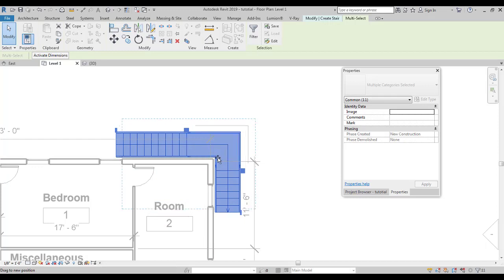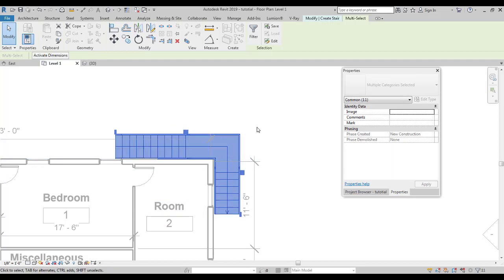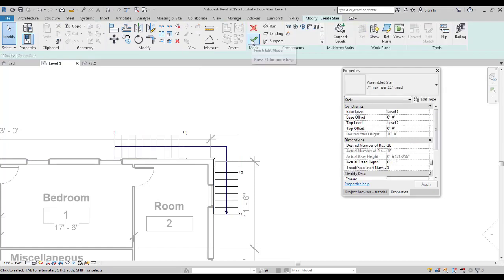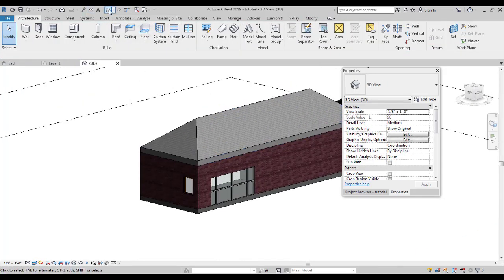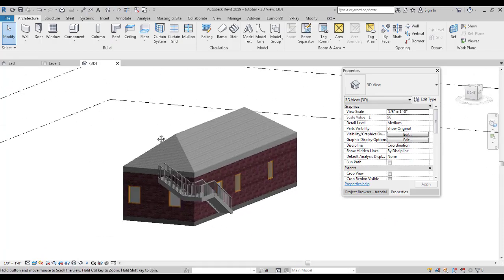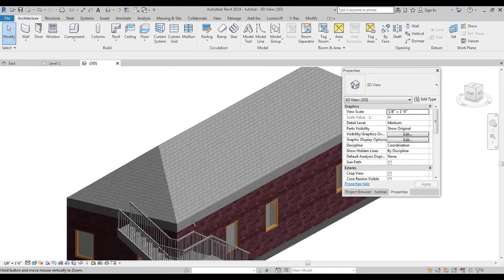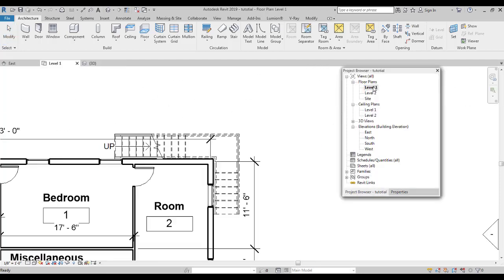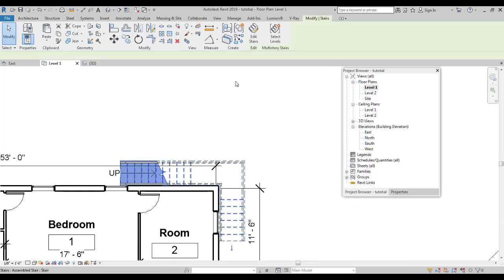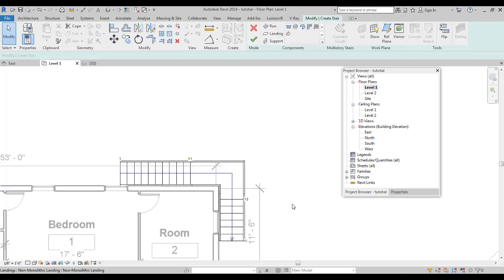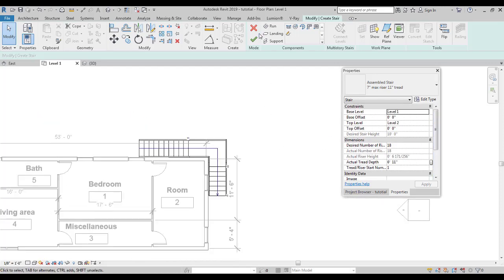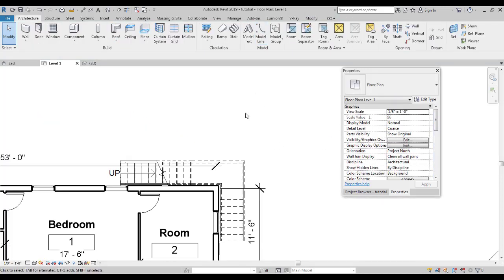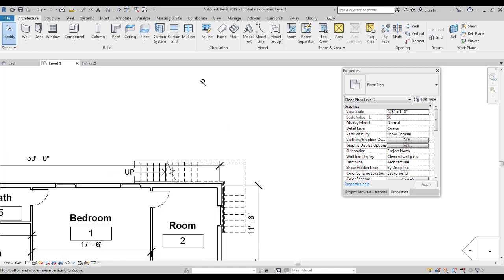And I'll just select stair and try to drag it. You can always use your arrow keys to get it in position. Click on the green check mark and voila, go to the 3D view. The 3D view, by the way, is over here, and voila, you have the stairs all drafted up. Now you can play around with stairs, you can change the properties of it, you can do a lot of stuff such as make them wider, make them shorter, do a bunch of different stuff, and I'll be going into the details of stairs in another video. And yeah, let's proceed further.